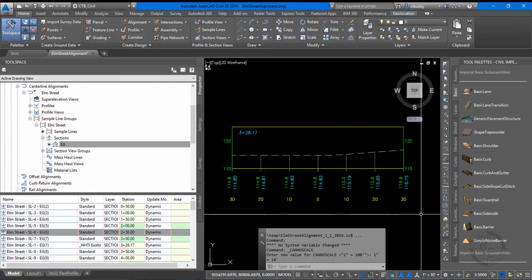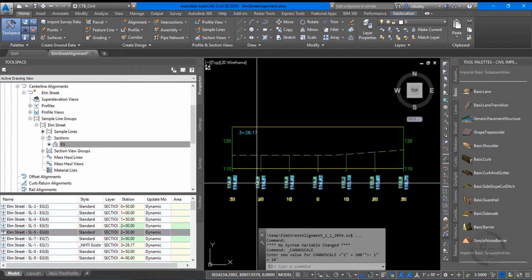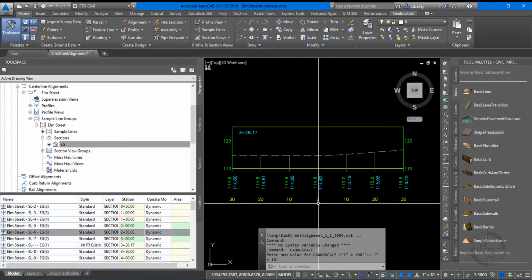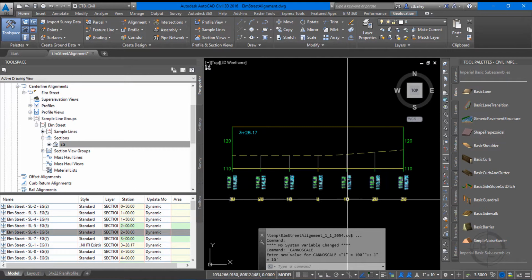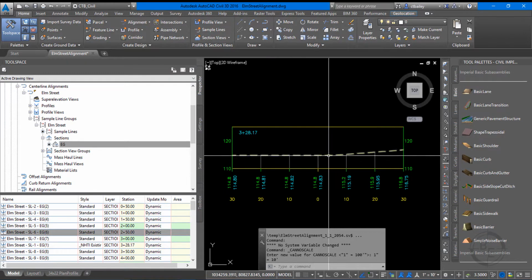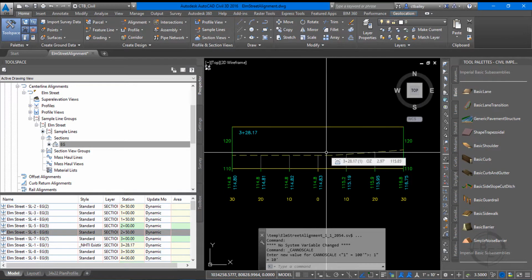We have the band showing the existing grade elevation and the finished grade elevation, and the offset. So here's offset 0, that's the center line of the road. That's 10 feet to the right. Here's 10 feet to the left. All right, so we are looking down the road, and it'll look more interesting as soon as we build a design road or a corridor. Okay.